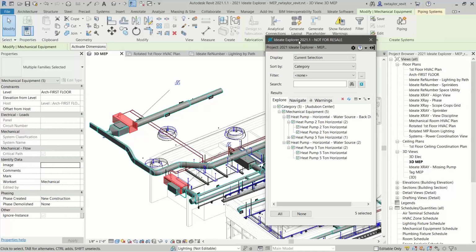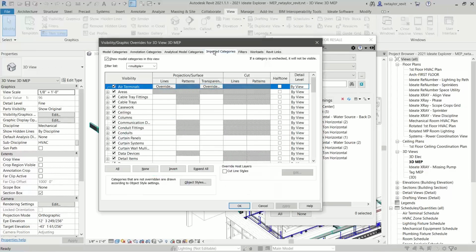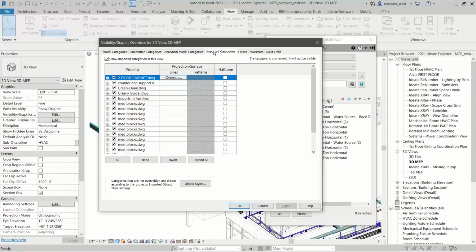And then we did get a question in the queue regarding deleting imported CAD files. Will it delete everything from the model? Not delete everything, but will it delete all the CAD information related to that import? Maybe you want to touch on that for a moment, Richard? Yes, if you've linked or imported the CAD file into Revit and you haven't done anything to it, it will delete.